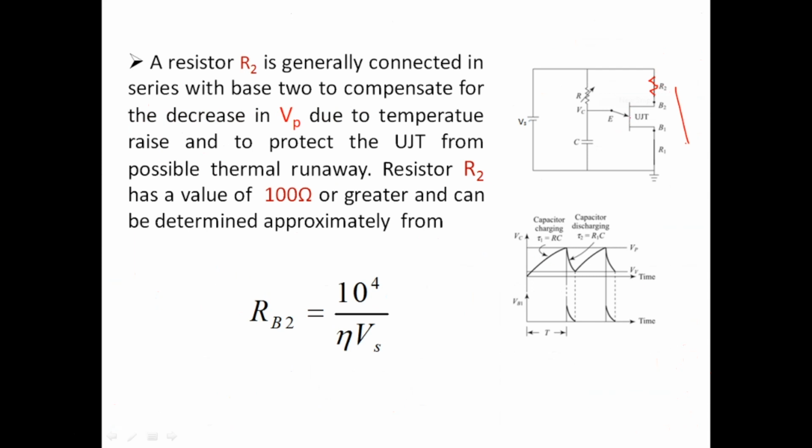As I told earlier, the interbase resistance between base 2 and base 1 depends on how many carriers are flowing here, so when the current reduces, the interbase resistance increases.